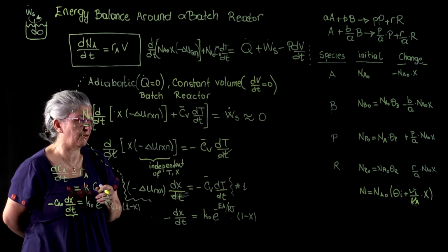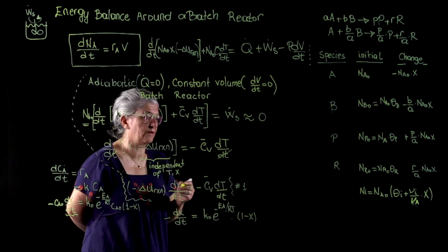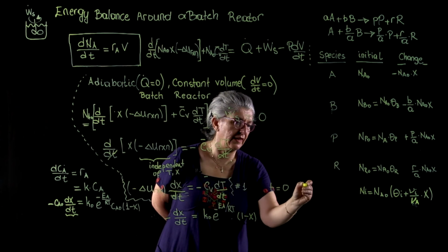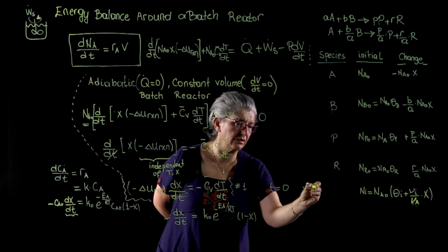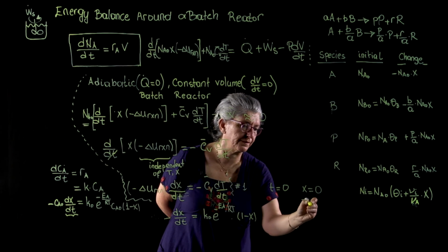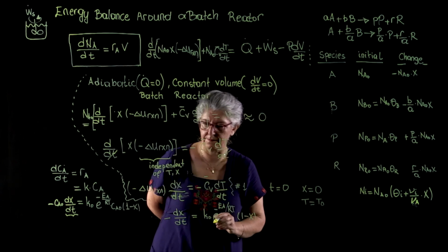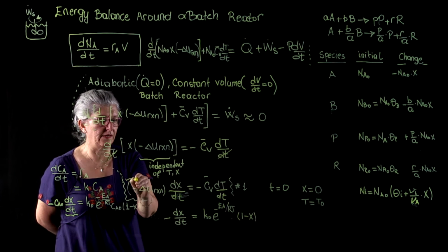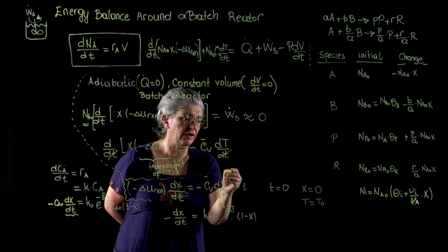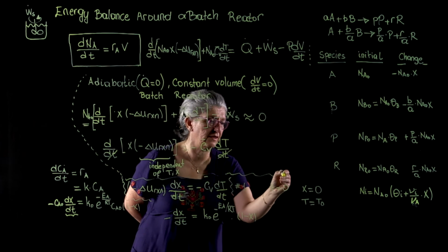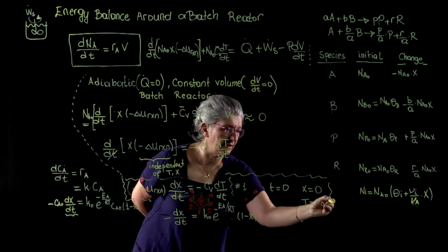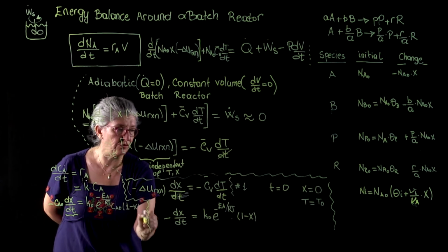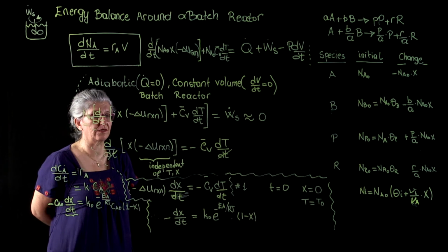In order to solve this equation, we need initial conditions: at time t equal to 0, x is equal to 0, no conversion, and T is equal to T0. Becoming familiar with the solution of coupled ordinary differential equations by numerical methods is going to take you far, and that is strongly recommended.